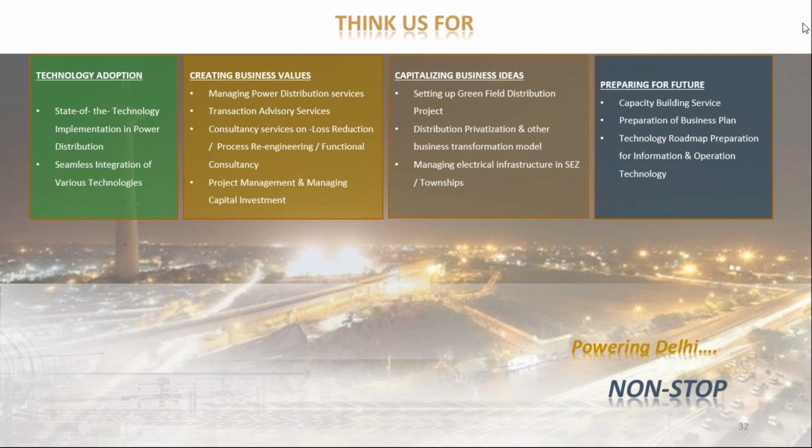Another thing that I would like to add, with respect to conductor, we also have to consider which conductor we are using. Are we using copper or aluminium? Because what we experience here in Karachi is that earlier in the distribution system we used a bare copper conductor, which was more prone to theft because copper has a good market value.